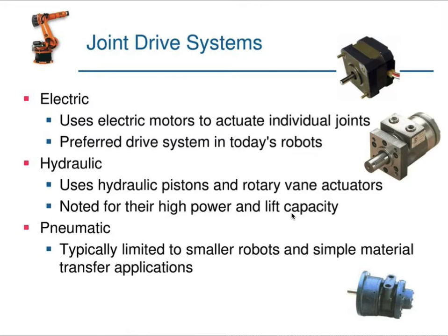The pistons are very simple and effective, and the hydraulic system exists in either linear or rotary form, isn't it? In the linear version, the displacement range is generally a few centimeters, while in the rotary version, the angular displacement is limited to about 270 degrees. An axial piston motor provides continuous rotation, but the technology is significantly more complicated.